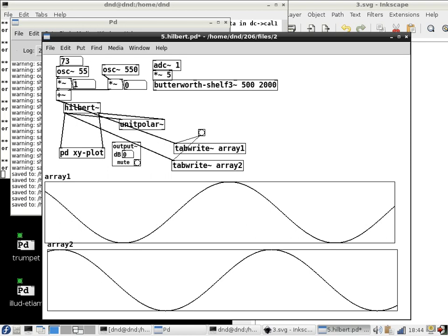Okay, so the phase shift in any kind of reasonable filter is a function of the frequency of the sinusoid that you pump it with. And the cool thing about the filters inside Hilbert is that they're amplitude preserving. They're all-pass filters. So any sinusoid I put in, I'll get a sinusoid out with the same amplitude, and all that will happen is there will be some phase shift. Now what you do is you find someone who knows the numbers and get two of these things that have the property that whatever the phase shift is, one of them is about 90 degrees ahead of the other.